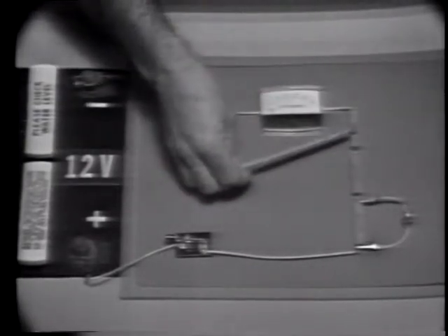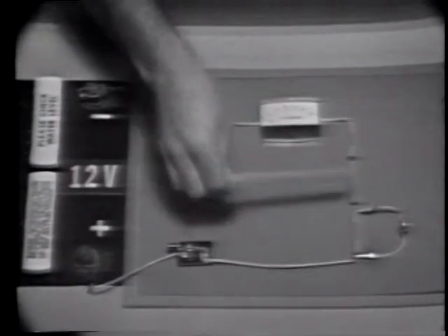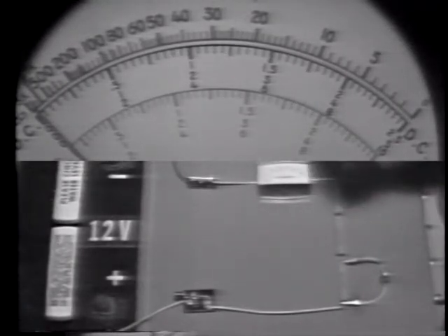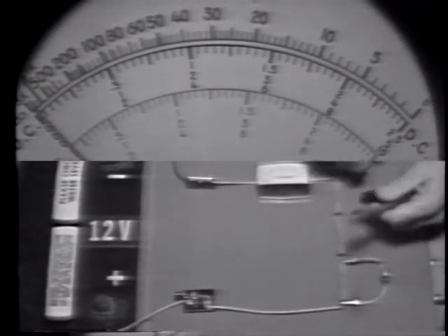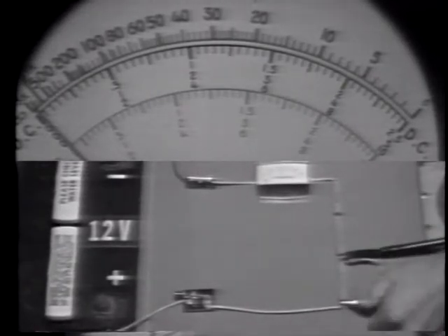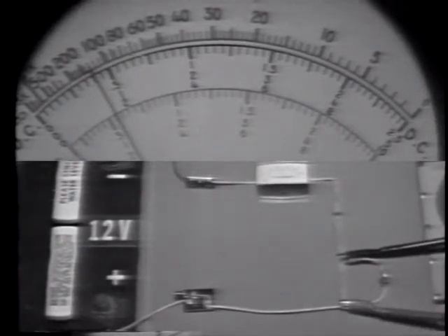Now, this current or load creates a problem. It changes the voltages developed in the divider. For example, let's use the voltmeter to check the voltage across this resistor. And of course, I must observe polarity. So connecting across this resistor and the load device, we find that it's less than 2 volts.